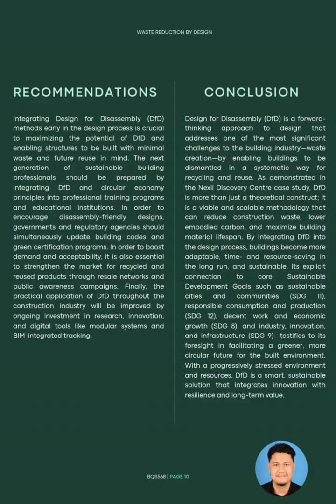To promote design for disassembly in the construction industry, I recommend 5 actions. First, start with early integration of DFD at the design stage, and then add DFD training into education and professional development. Also, government should offer regulatory and financial support. This is to strengthen the reuse market through public campaigns and better infrastructure. And lastly, invest in innovation, digital tools, and modular systems to make DFD more efficient and scalable.